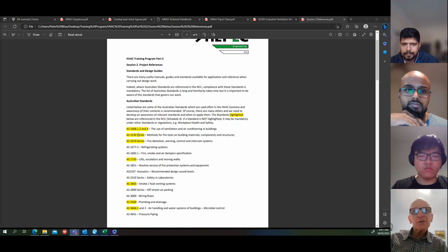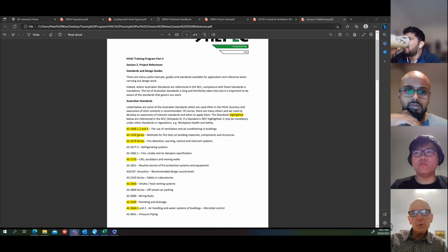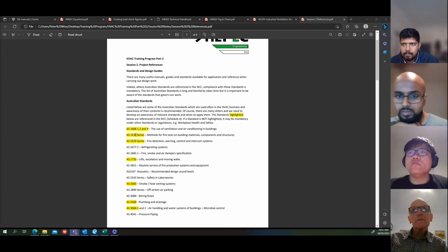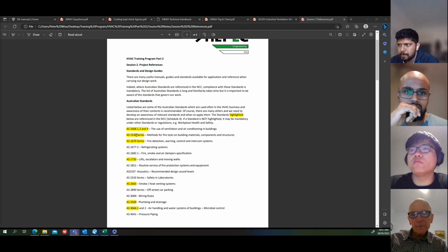And AS 1530 Part 4, for instance, is for fire rating. And as you go along through your careers, this will come up again and again. It's not that you have to refer to the standard, but you need to be aware of it because with fire-rated ductwork, it becomes very important.